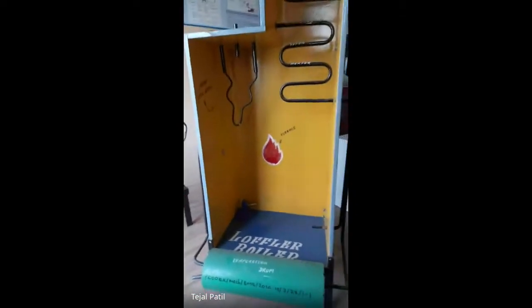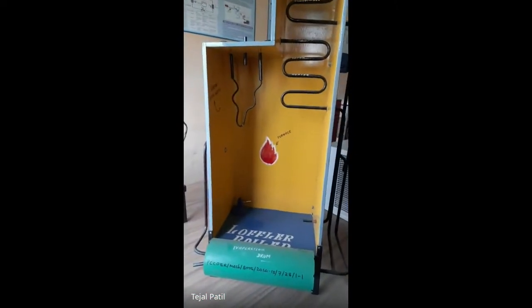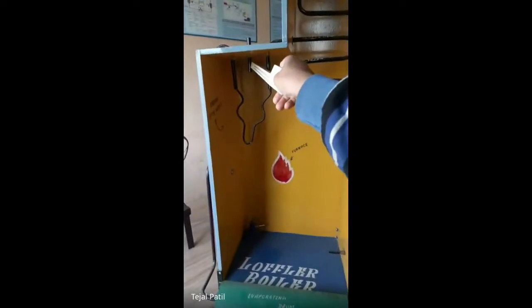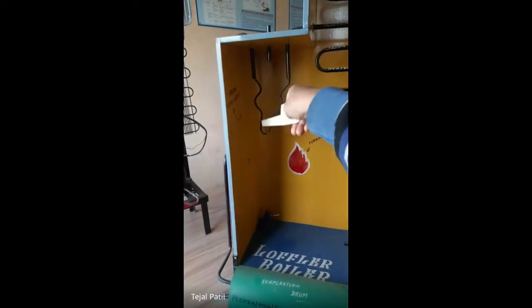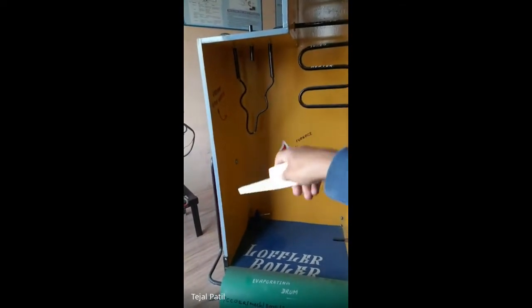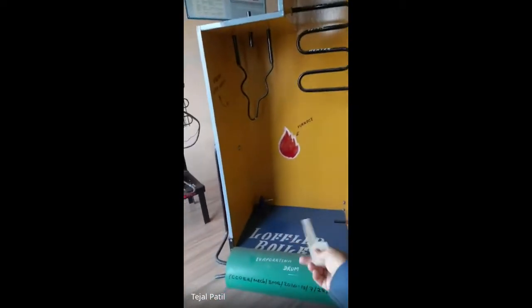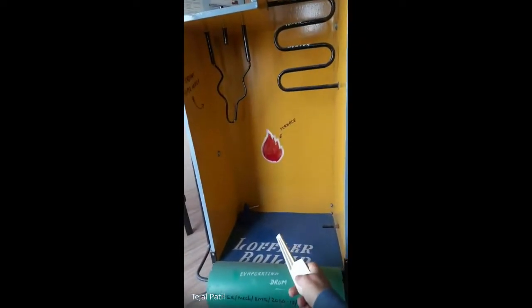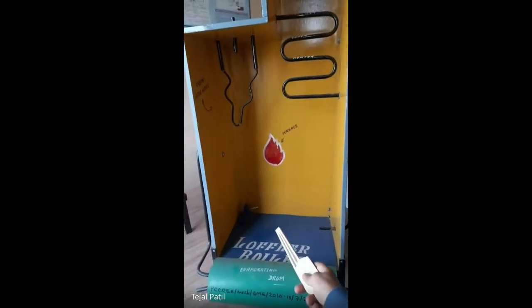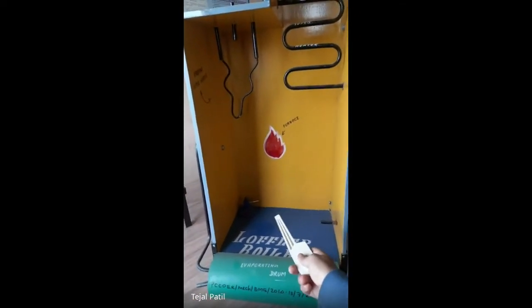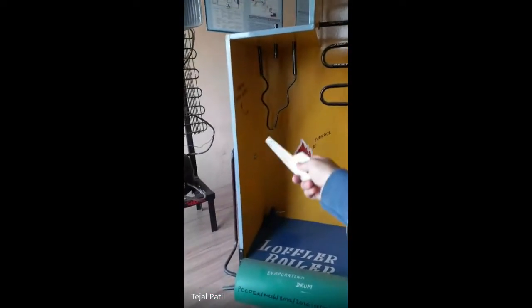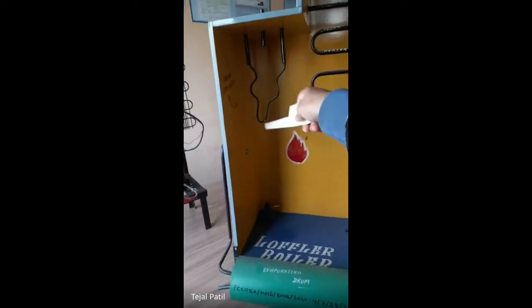Okay, but before going to that, let's understand basically how is the flow of the fuel here. Flue gases. So this is the entry of the fuel. From here basically oil is splashed, and it will catch the fire which is already burning inside the furnace. This is the point from where the air is going to enter, and it combines with the oil, and a burning action will take place, and it gives you the flue gases which are at very high temperature. The highest temperature will be at this point.